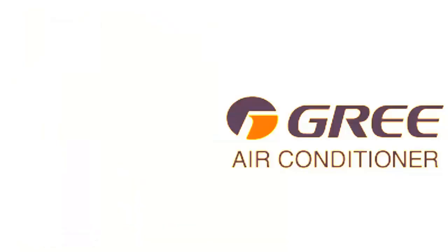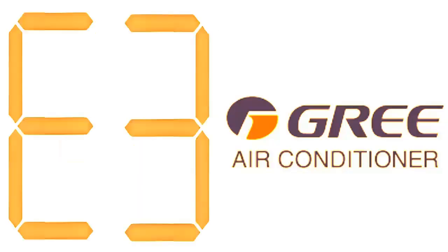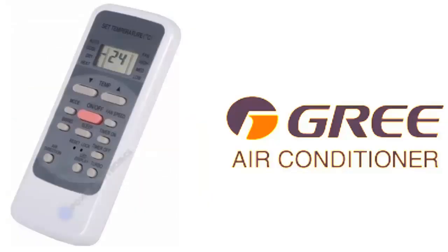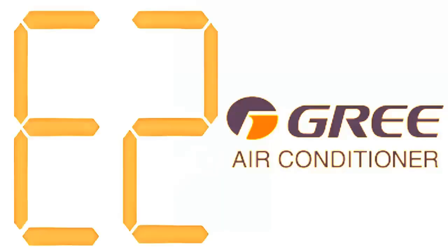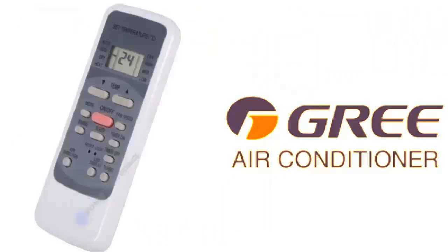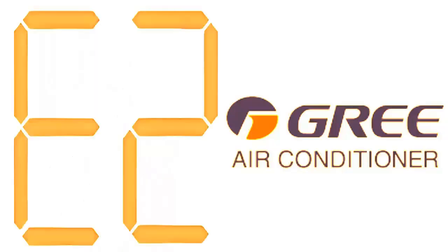Before delving into the detailed analysis of error codes E2, E3, and E4 for Gree air conditioners, remember as a first step that when troubleshooting a unit, try turning it off and unplugging it from the power source for several minutes. Then, turn it back on and check if the error code reappears. If the error persists, follow these steps.